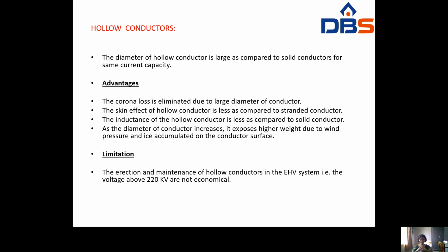The name itself indicates that this is hollow in shape. The diameter of the hollow conductor is large when compared with solid conductors for the same current capacity. Coming to the advantages, the corona loss is eliminated due to the large diameter of the conductor. Next, the skin effect and the inductance of the hollow conductor are less compared to the solid conductors. Next, as the diameter of the conductor increases, it is exposed to higher weight due to wind pressure.